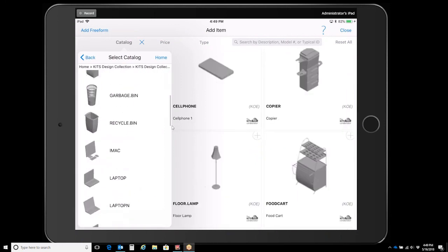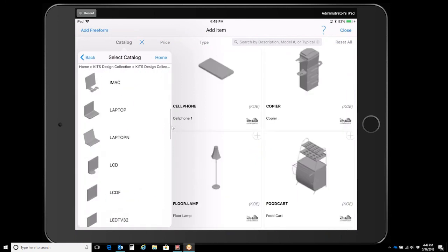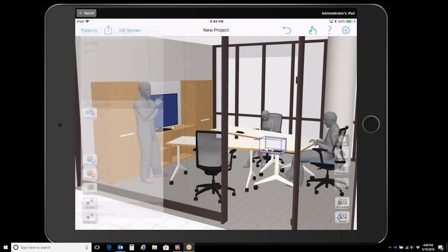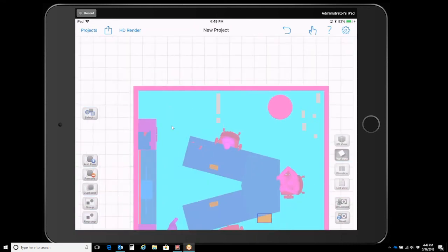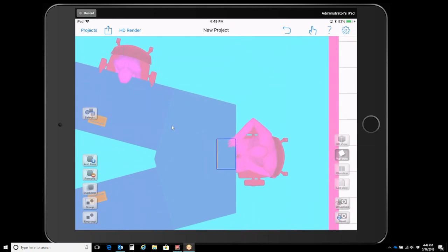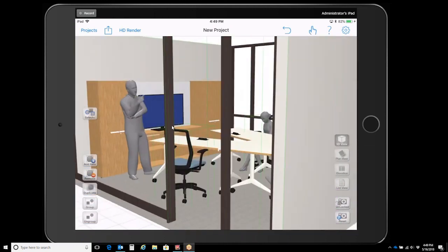And we're going to spin this. So it's like the client is using it. Let's look at 3D view. Looks like it needs to be raised, so we're going to use a 3-finger gesture. And well, let's go ahead and turn off snap to, so it'll snap to the top of the table. That looks pretty good. Let's add some color to the people.